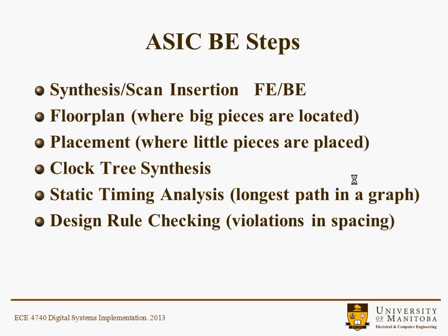We'll look at design rule checking. That's low-level design rule checking, and these might be violations in the spacing when you're basically drawing polygon blocks that are going to be implemented in silicon. So it might be making sure that two metal layers are far enough apart that there's not a chance of them touching one another, causing a violation, or perhaps even an electrical rule check where there might be some crosstalk that you're trying to avoid. And at some point you'd like to be able to verify the layout versus the schematic to make sure that they basically are representing the same structure.